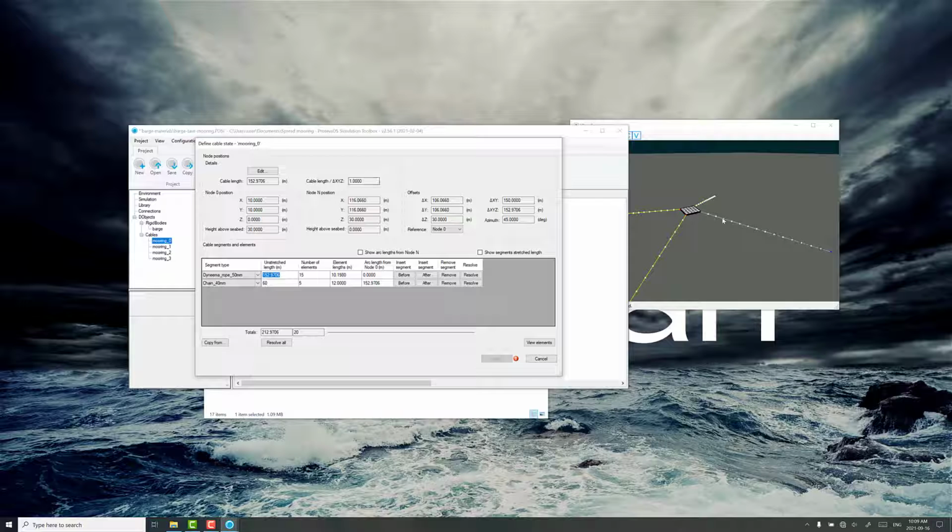One thing we want to do, though, is make a slight adjustment to the line, because it's taut here, and that's fine. We can resolve what the static loads are going to be like in a simulation, but I think we can do a little bit better. So what we'll do for a mooring like this, we'll take a look at how the deflection changes when we relax the cable length to the offset of the anchor.